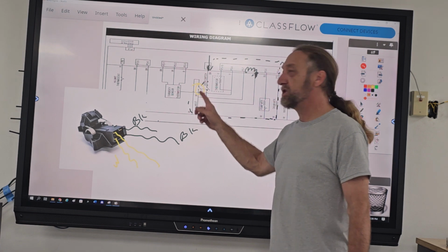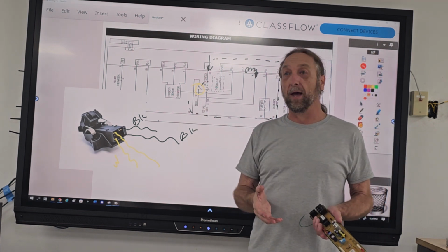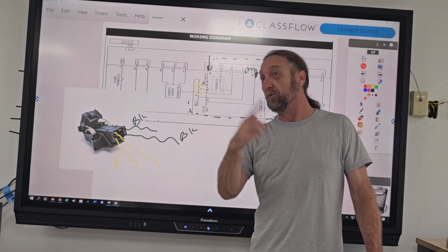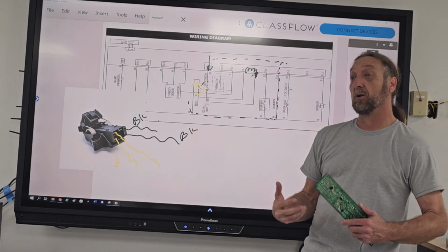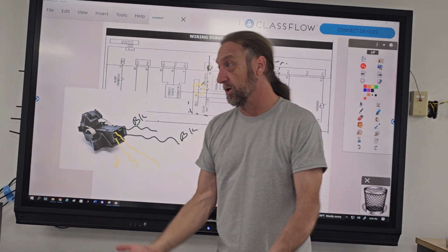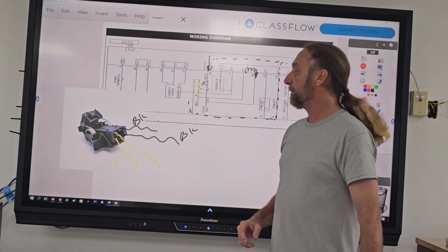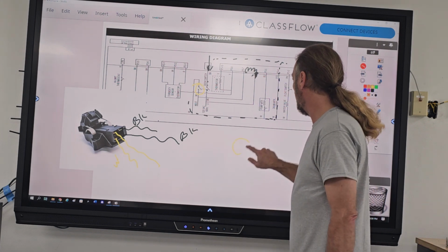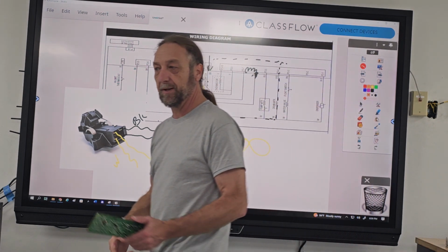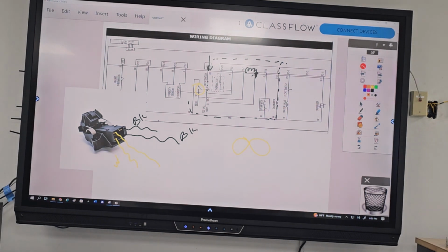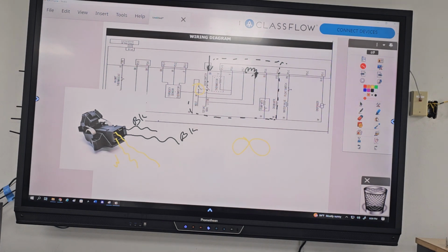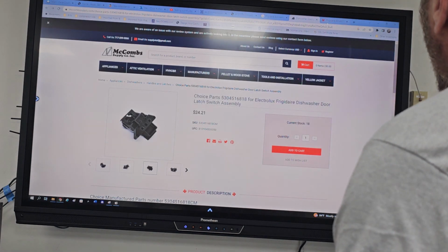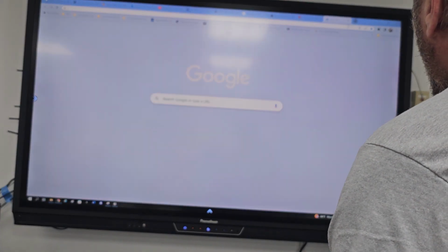So if the switch is bad, the digital meters say OL, but if it's an analog meter, it don't say nothing, you have to read it. And that means infinite, means it's open. Infinite's another example for total resistance, no electricity can pass through. Is that the funny H shape? Yeah, that means infinite. And you know, it's on the analog meters. Let me show somebody, because they might not know what we're talking about. So, I forgot what that meter was that I got from Amazon, but let's go there.